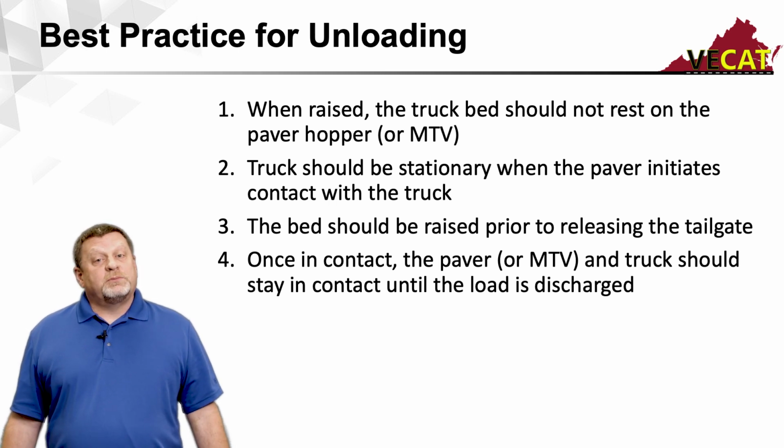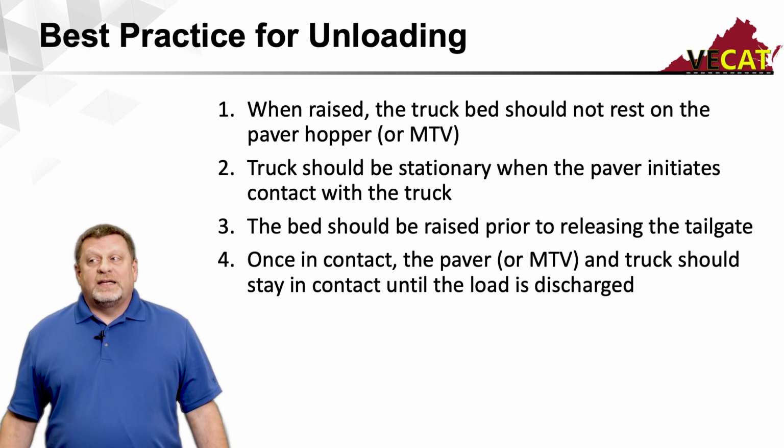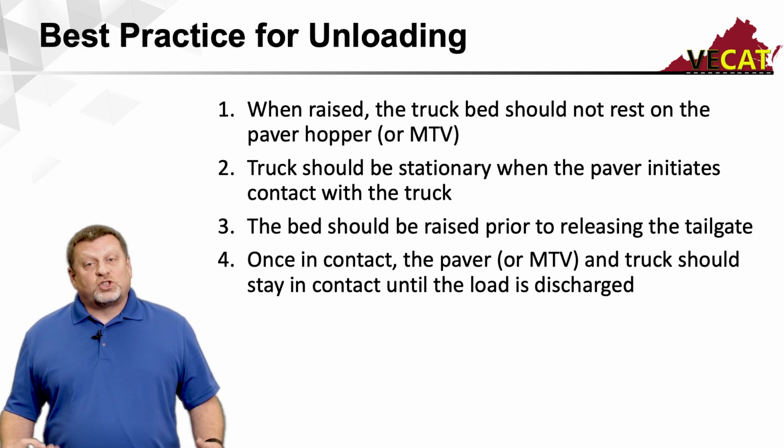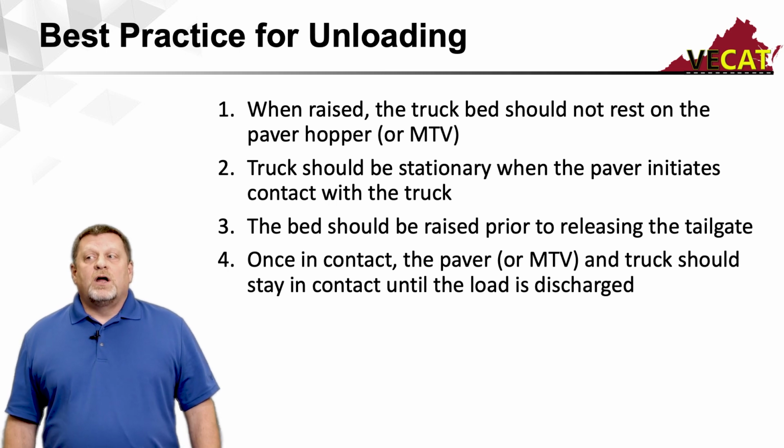The bed of the truck should be raised with the tailgate still locked. So you want to get it up about a quarter of the way and then release that tailgate. That will allow the mix to come out of the bed of the truck in a solid mass and not trickle down and just roll. This can induce segregation. So it's important that you start raising the bed of your truck prior to releasing the tailgate.